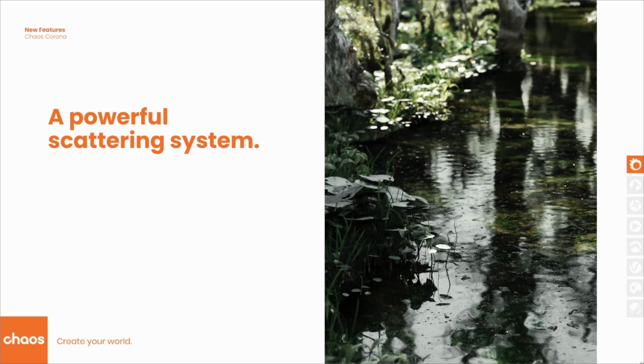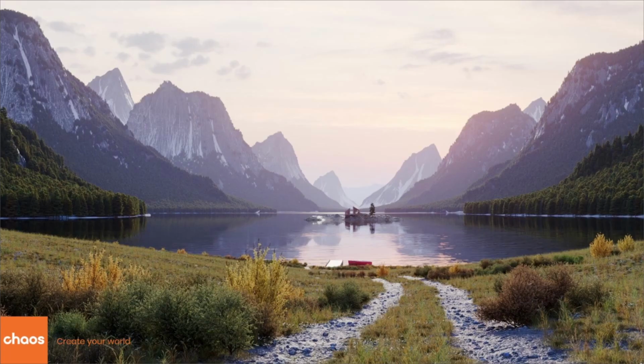Now let's take a look at some of the images that were created with Chaos Scatter. So this is a pretty big one. As you can see, you can scatter a ton of high poly assets, and so you can create landscapes such as the one you see in front of you. Now, Chaos Scatter has got some really nice functionality built in. If you take a look at those mountains in the background and how the trees grow on them, you can see that as the slope gets steeper, the fewer trees you'll see instanced there. And that's really easy to set up with Chaos Scatter because it's just a matter of tweaking the slope parameter, so just a single parameter essentially.